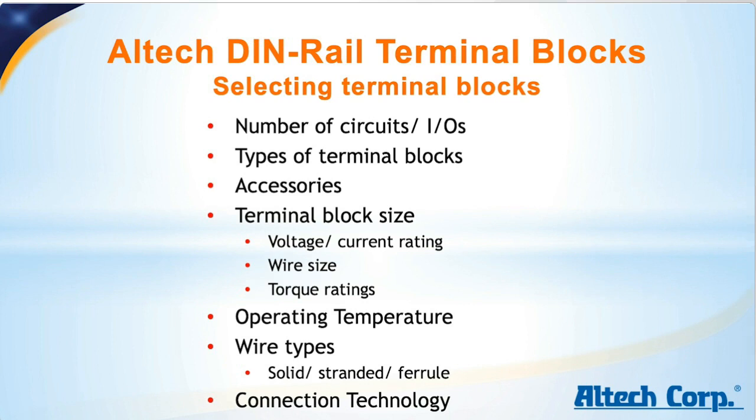Many terminal blocks, they come usually in different sizes. The size of a terminal block is determined by its required voltage and current ratings. And also important is the wire size or what wire types is used. We want to make sure the needed wires fit into the terminals, and also we don't want to oversize the terminal blocks to keep the whole system cost effective.